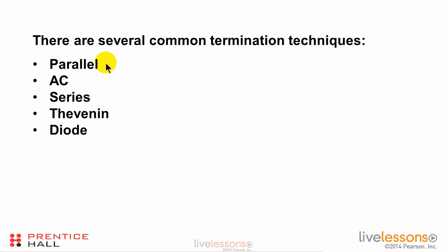Now, there are several common termination techniques that are used. They go by the names parallel, AC, series, and then Thevenin and diode. The first three of these are pretty common on circuit boards. The last two really aren't very common.